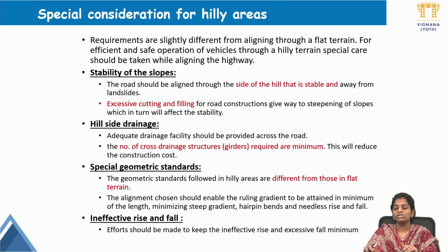The road should be aligned to the side of the hill so that it's stable and away from the landslides. Landslides should not happen. Hillside drainage is also very important. Vertical drainage, horizontal drainage, everything should be taken care of. Special geometric standards: flat terrain has different geometric standards and hill terrain has different geometric standards, so all those should be followed. Then, ineffective rise or fall. Steep slopes or very deep valleys should not be constructed because there will be an issue of safety.